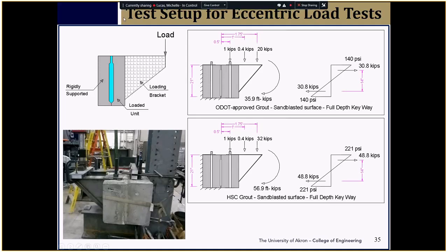This test was kind of tricky in the sense that we need to apply the desired amount of shear load and the out of plane movement, and they should be in proportion to each other in such a way that we are not increasing just the moment or just the shear, but they are simultaneously loaded to the same level with every increment of loading.